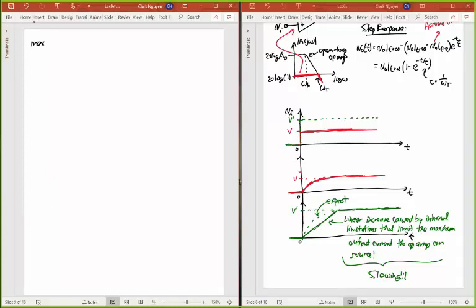Let me just say the maximum rate of change of the output voltage, that's called the slew rate. And it's often also abbreviated SR, and that's equal to the derivative dV0/dt, the maximum dV0/dt that the op-amp can source, and that's going to be in units of volts per microsecond, is usually the units that people will use for that. Okay?